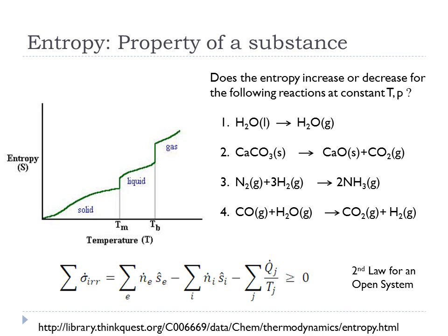Okay. Now, in the third case, we have the case in which the entropy of the species leaving is actually less than the entropy of the species entering. So what does that mean? What that means is that we need to have heat leave the system and carry some entropy out of the system in order for this to take place.